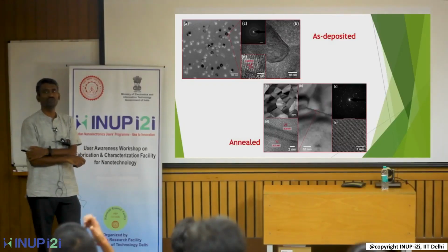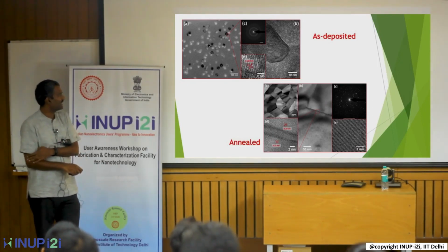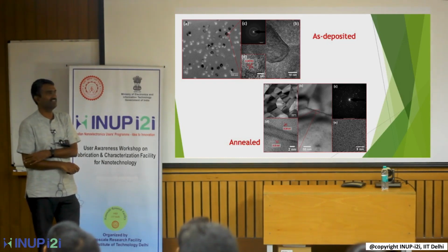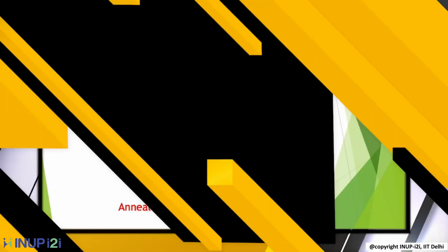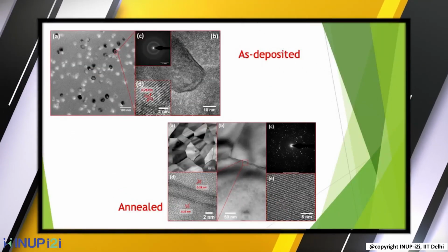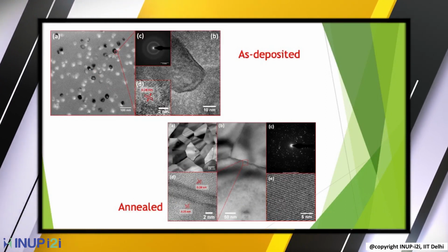Epitaxial film, right? Growing a crystalline film on a crystalline substrate. Those techniques are molecular beam epitaxy and liquid phase epitaxy. But here we don't do that, we just make the film, so this is polycrystalline. Based on this, after annealing you can see several types of grains. Here the charge carriers, whenever they see a grain boundary, are going to have grain boundary scattering, apart from lattice and ion scattering. So these are all going to influence the properties. That's why the size of the grain is very important when you make it.